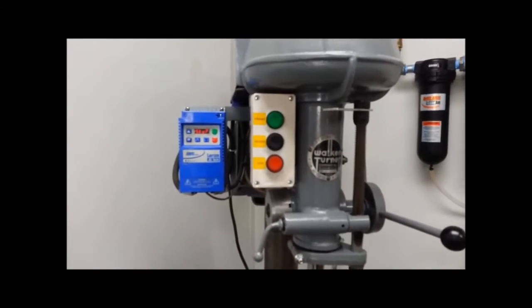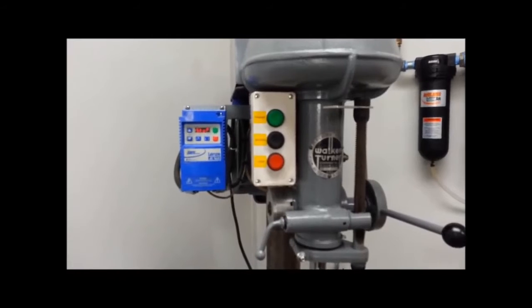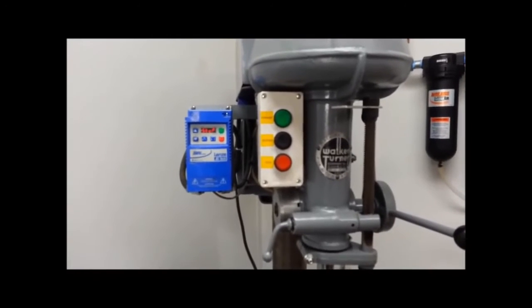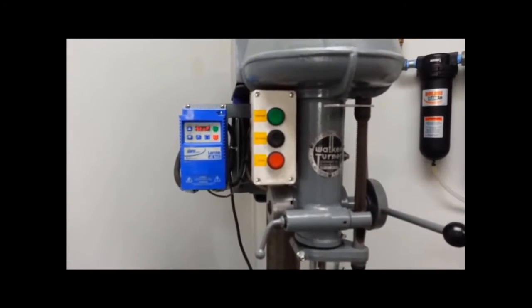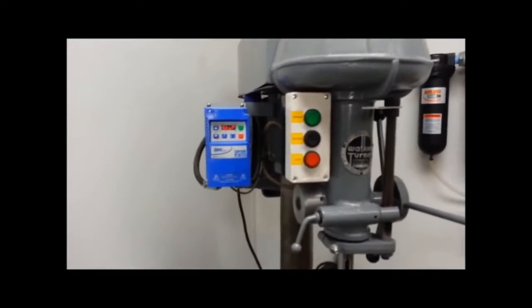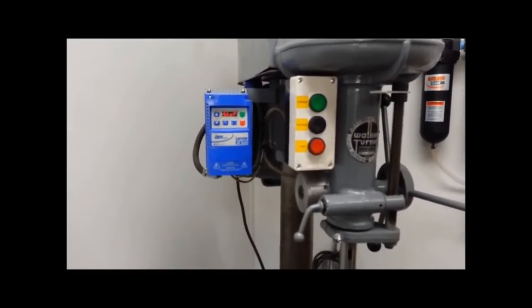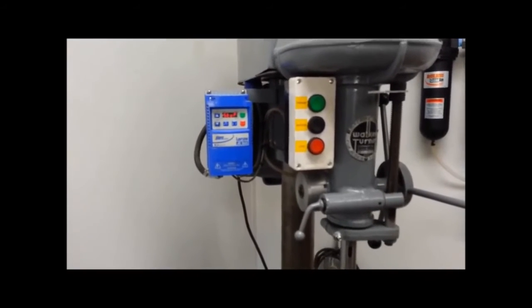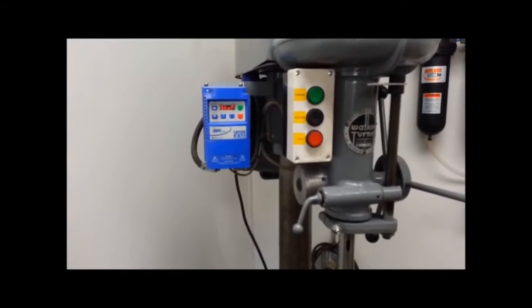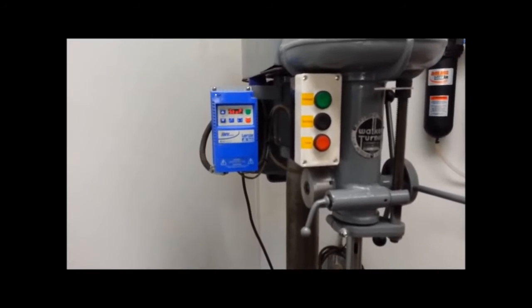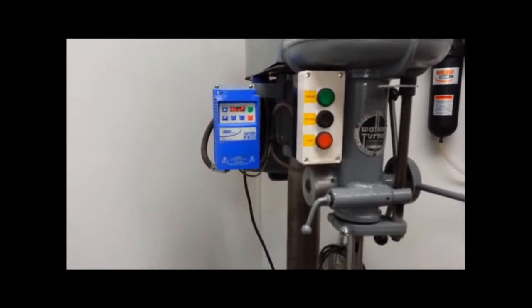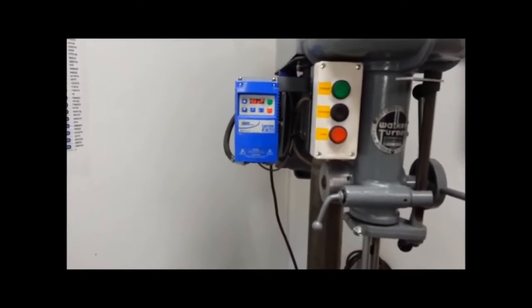You've only got 2 poles to drive within that motor, and you've got more of a chance for that motor to slip, and you can't get the torque out of them. But if you do the same thing with a 1,700 RPM base motor, now we're working with a 4-pole motor, and there's less of a chance of it slipping at the lower speeds. So you don't have to boost your vector control up as much.